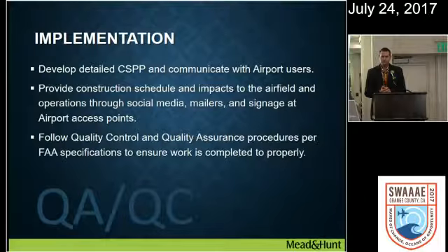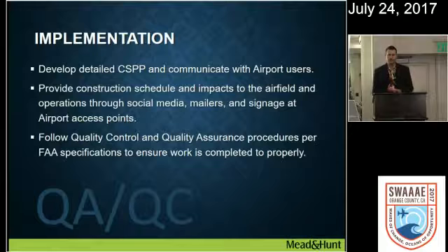So one other element that a lot of these changes has caused, or not caused, but the removal of pavement markings. So on an airfield, the pavement marking requirements change, or your airport design group changes requiring the markings. It's a challenge. With the new advisory circular, you have to remove the markings in a box type fashion. And so I just wanted to share a few lessons learned on that when you're trying to implement these new